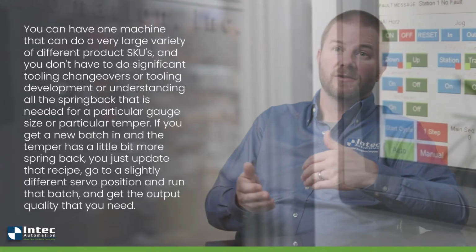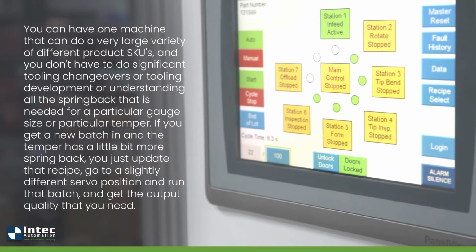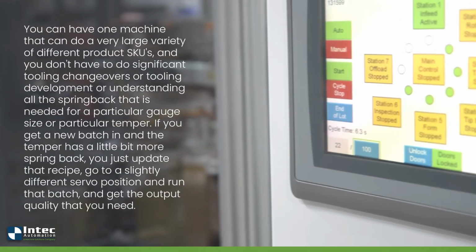So in that approach, you can have one machine that can do a very large variety of different product SKUs, and you don't have to do significant tooling changeovers or tooling development or understanding all of the spring back that is needed for a particular gauge size or particular temper. If you get a new batch in and the temper has a little bit more spring back, you can just update that recipe, go to a slightly different servo position, and then run that batch and get the output quality that you need.